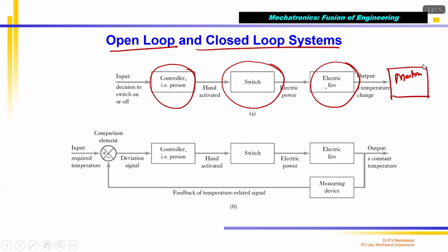So, for example, you take an engine. In open loop control, I have the engine, and the engine needs to be controlled. Here we have an injector, which is the actuator, and it needs to be driven by a power amplifier, because the injector works generally at 12 volts.